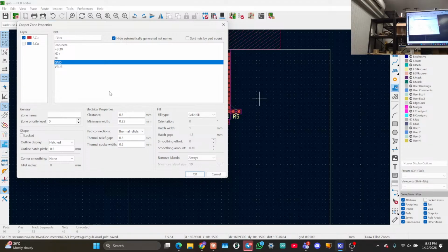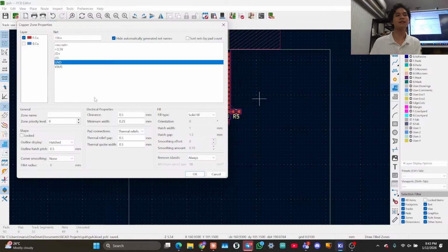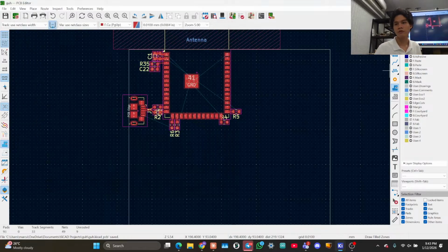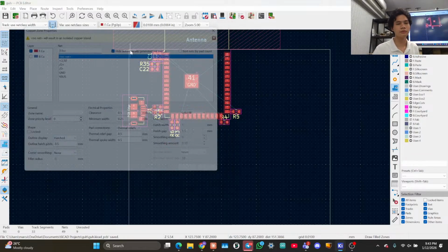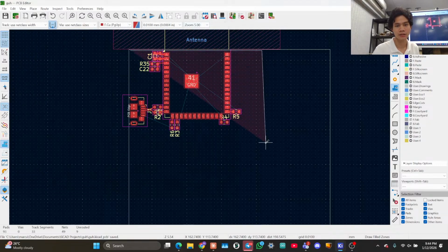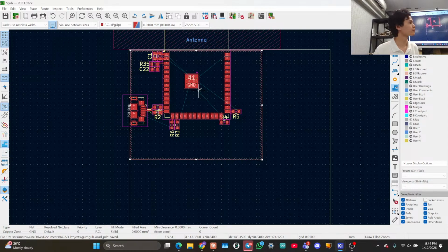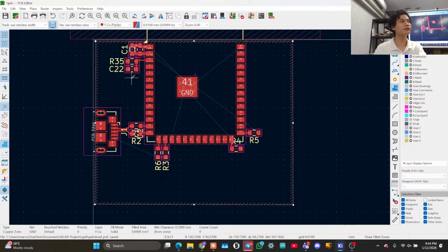Guys, you need to be on a copper layer. Go to the front copper layer because that's where all our parts are. So front copper layer, then click ground. Now we're going to draw a bounding box like this. 1, 2, 3, and on the last point we double click. Now I've got this serrated bounding box. Have I lost anyone? Now I'm going to press B.